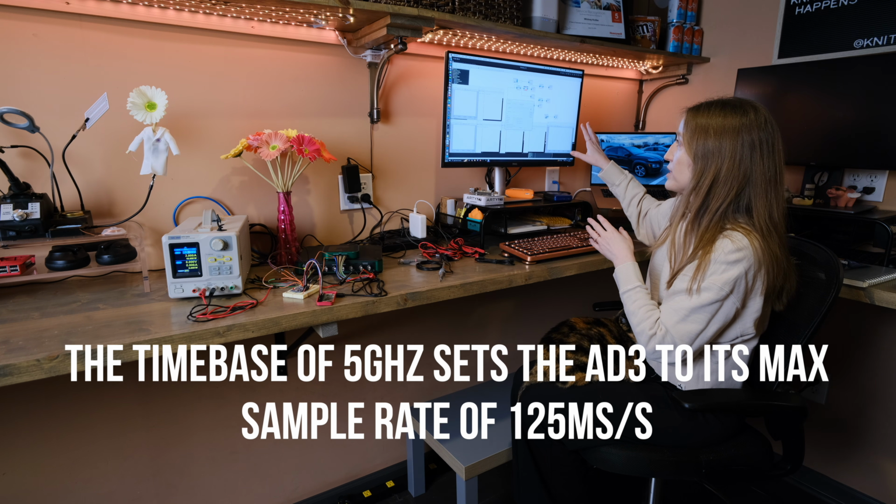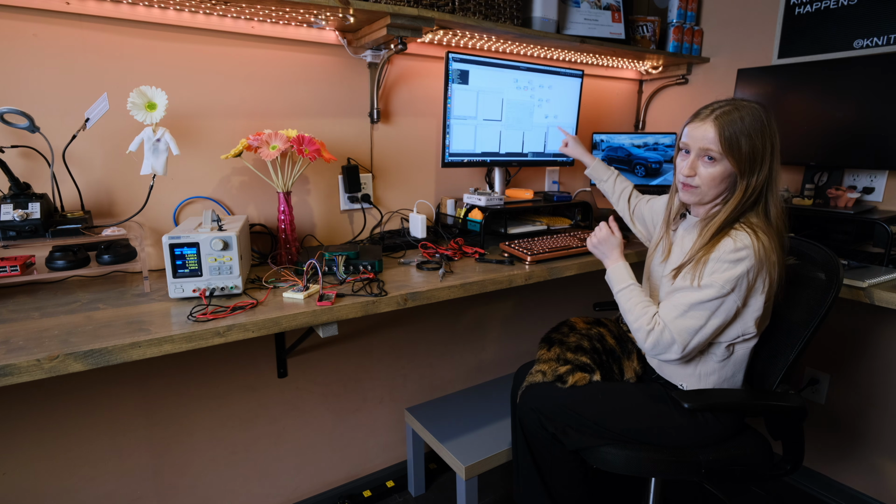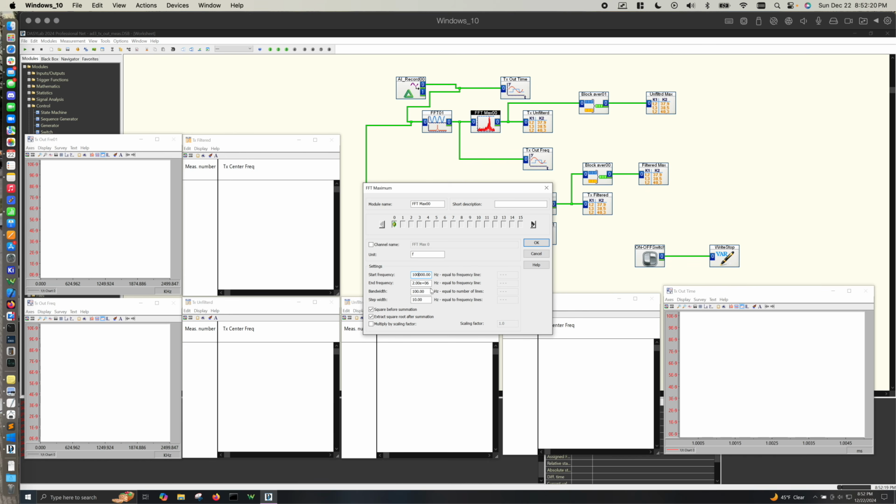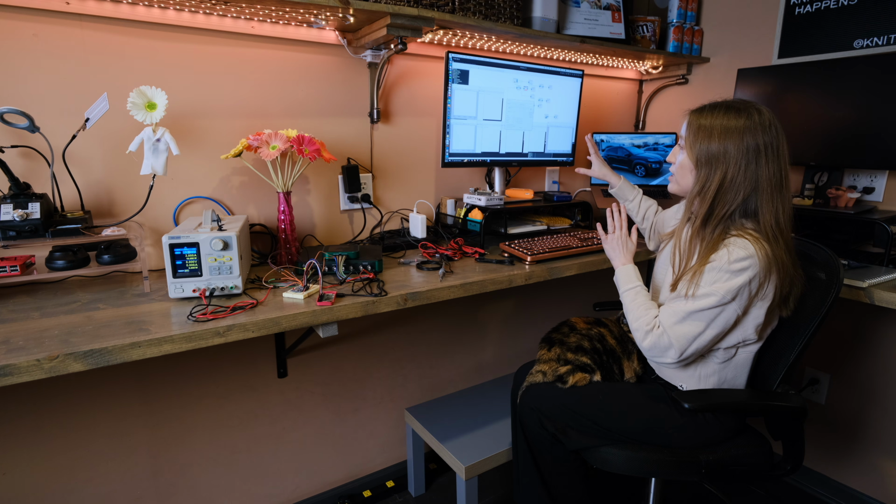The measurement setup sampling rate of DASYLab, so the sampling rate of this FFT block, is 2 gigahertz, or 2 gigasamples per second. So I have my start frequency at 100 kilohertz going all the way up to my maximum, which technically is half of that, according to Nyquist. But I have the end frequency set to be the same as the sampling frequency of the worksheet.